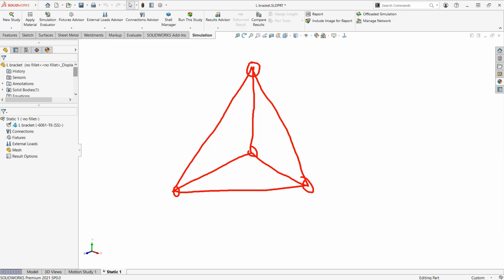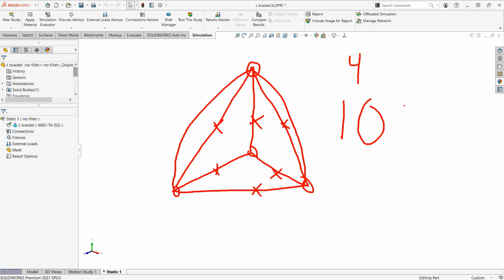If you switch then to high quality elements, what you do is you add what we call a mid-side node, in the middle of every element side. Now, there's 6 sides, so it's 6 additional nodes. That gives us a 10-node element as opposed to a 4-node element. What that allows you to do is then have this definition of these element edges be curved or parabolic. So the implications there are actually pretty significant.